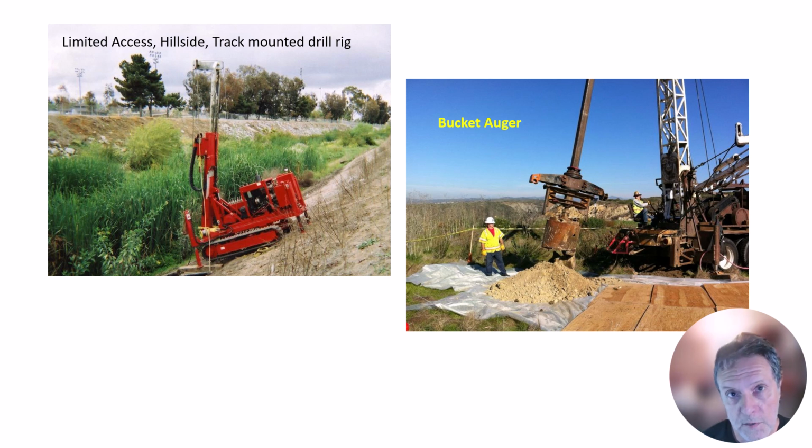I'll tell you, I've been down a lot of these types of holes. The deepest hole I went down was 118 feet. It's not for the faint of heart. It's something you have to be careful with. You have to lower gas meters down to make sure there's no toxic gases in the hole. And you don't want to obviously go down below groundwater, because you can't log anything while you're underwater. And in some landslides, typically, or sometimes, right at the contact between landslide deposits up above and solid stable ground down below, you usually have groundwater sitting on top of that plane at that depth.